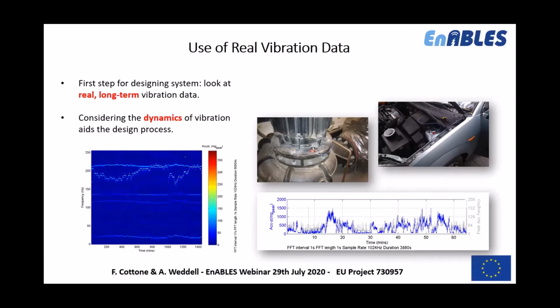You can see there's a mixture of vibration signals within that trace. The dominant vibration in most cases is from the rotation of that motor, and it changes its operating speed based on the demand for hot water from various parts of the campus.